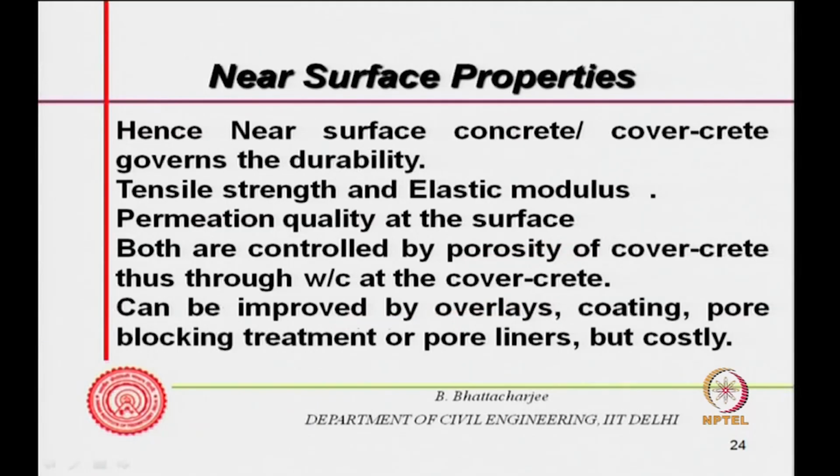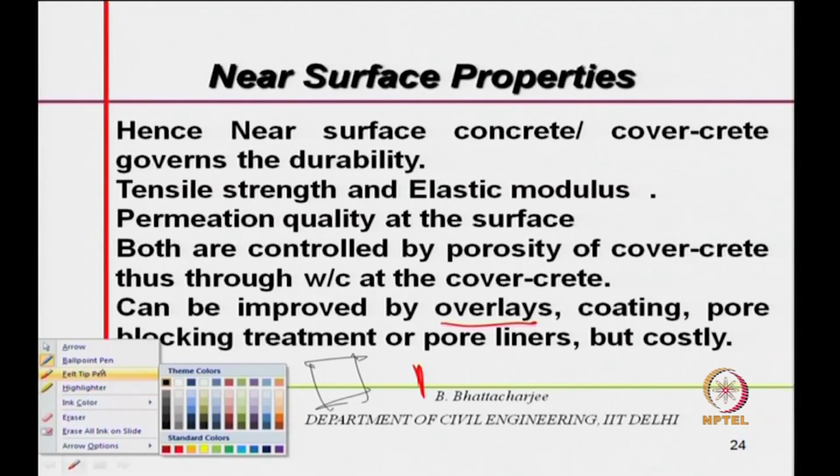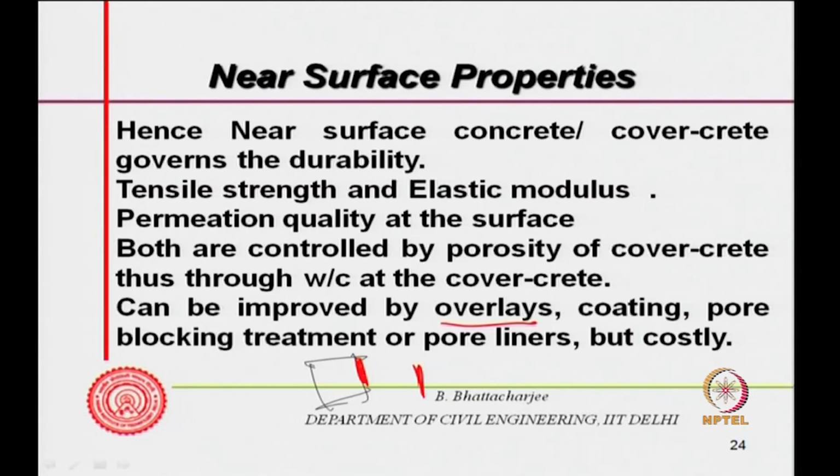We can improve the cover concrete by overlays, put a thick layer. This is your concrete, let us say, this is your original concrete, put a cover layer, put a layer here. So, that is overlay. Coating, put a coating here, put just a coating.